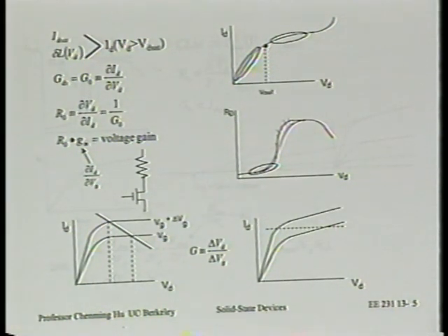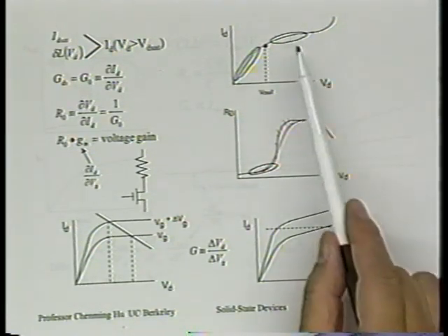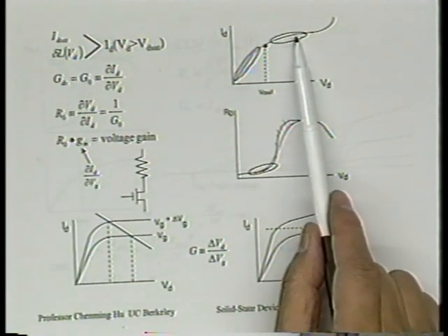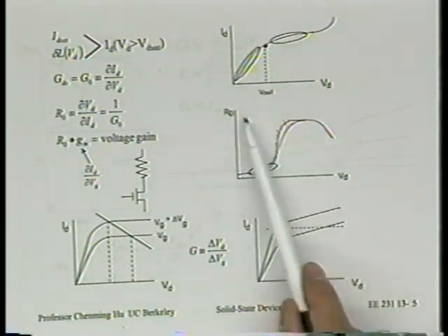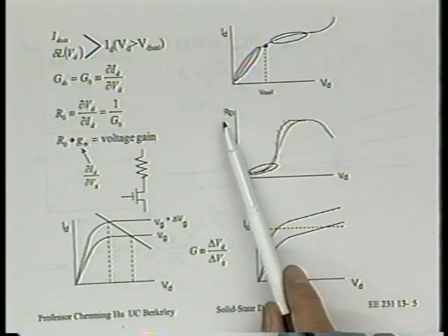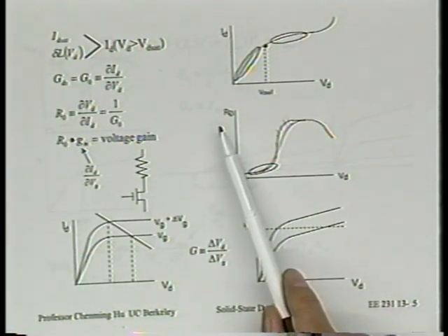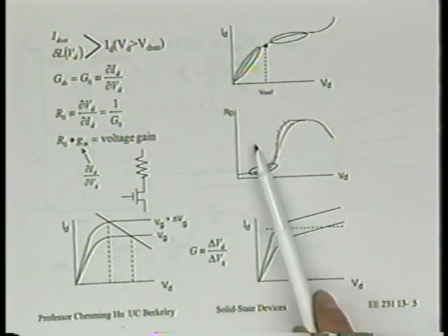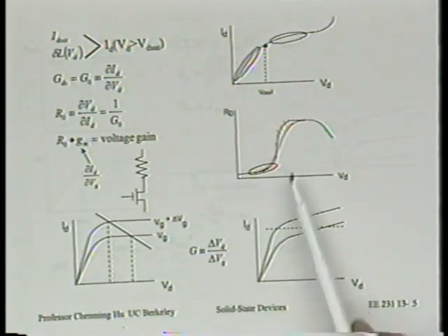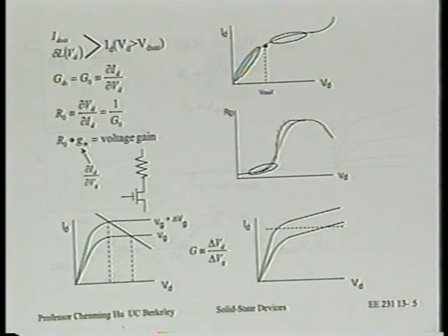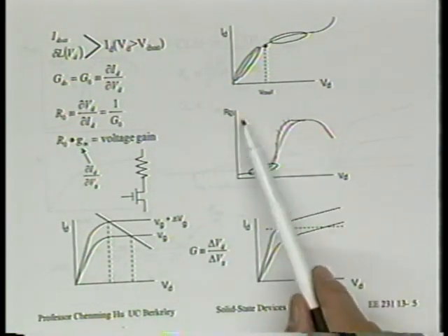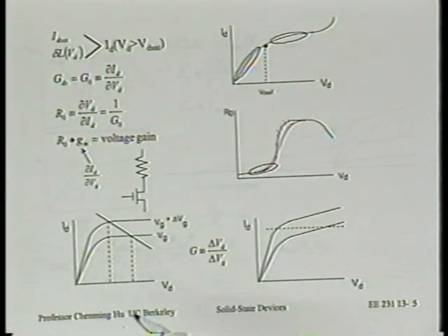So this is the general characteristic, and therefore this is really where we can design a good high gain circuit. That's why we like to plot this as R out. If we plot G out, guess what this curve is going to look like? Where it's really most interesting, it's almost zero. You don't see it. The curve mostly emphasizes where it's not interesting and not useful. What's really important is what we want to emphasize. Therefore, often you see data presenting R out rather than G out.